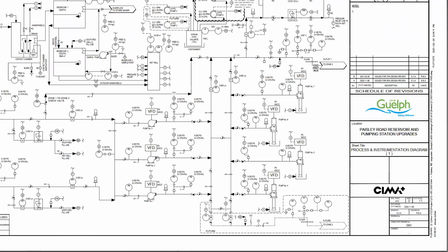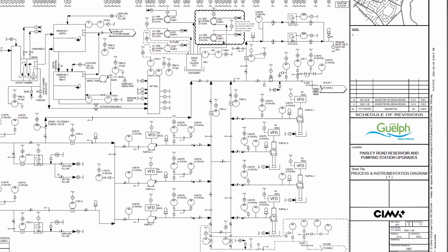The water from these booster pumps will travel up here, won't really travel down here because each one of these pumps will have check valves, so we can't flow that way. We're going to leave through the zone 2 outlet. We could also do pressure relief.